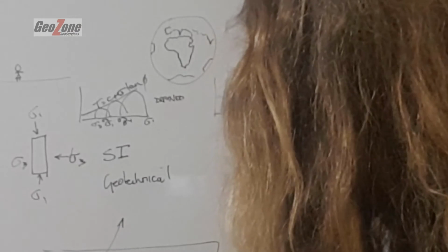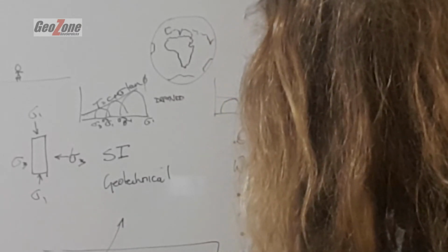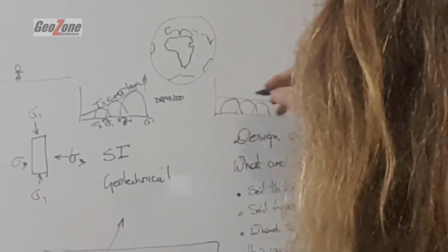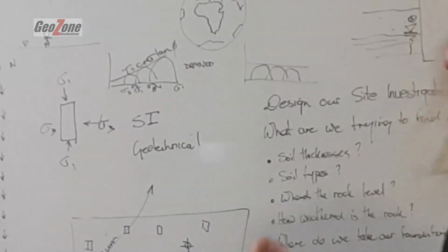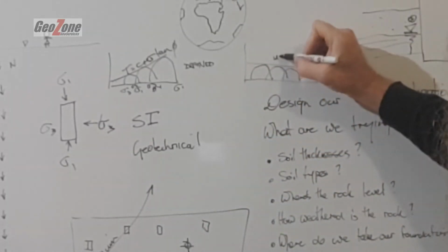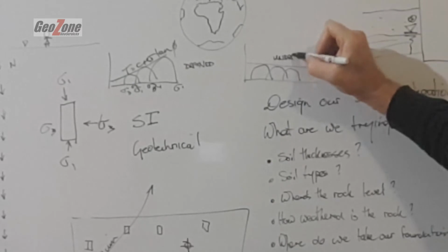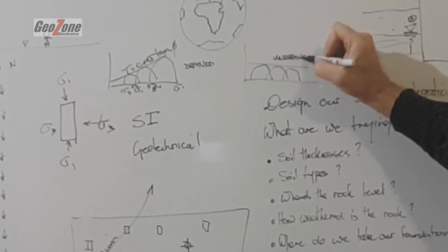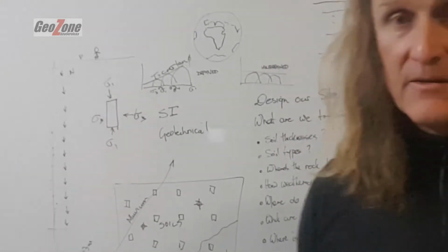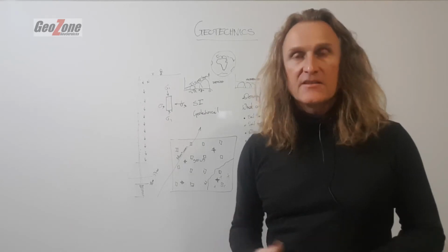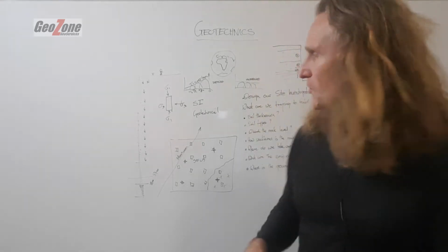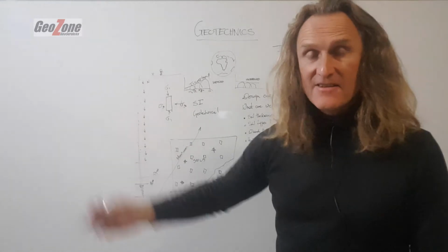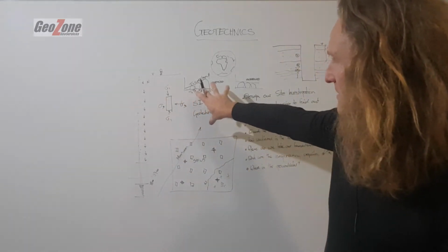Drained, if we do those tests, sigma 3, sigma 1. So there's the undrained version, which is reflective of the immediate conditions, saturated after excavation takes place, or the drained version where the slope has had time to drain, and then we get a different scenario playing out.